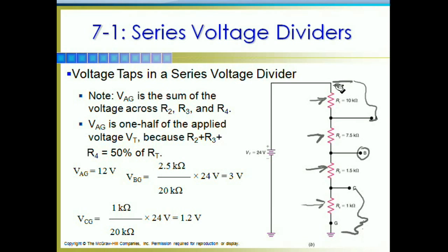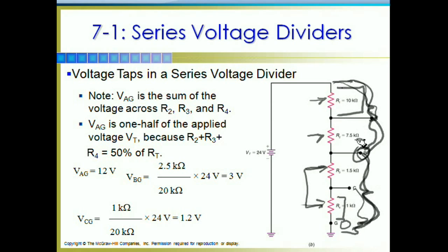Getting point B, I have to either add the 2 voltage drops there or the 2 voltage drops here. Okay, in this case I had 1.8, pardon me, subtract the 2 voltage drops here, because we've got to remember we're going down to ground, or add these 2 voltage drops, because we're measuring B to ground. So it's across these 2 resistors for B, but C is a single R4, A is a simple R1. I hope I didn't just confuse you there. Yell at me if I did.